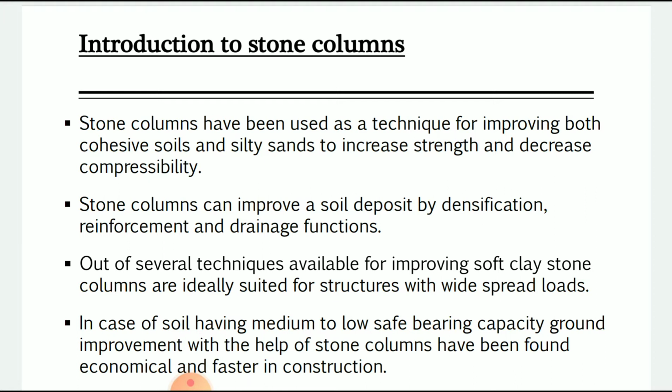Always remember, when you are going to adopt the stone column technique, how the stone column can improve the soil deposit with three terms, that is D, R and D, or D square and R. How is it? First is densification, second is the drainage function, and thirdly reinforcement.